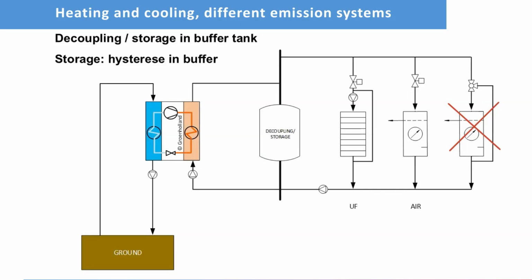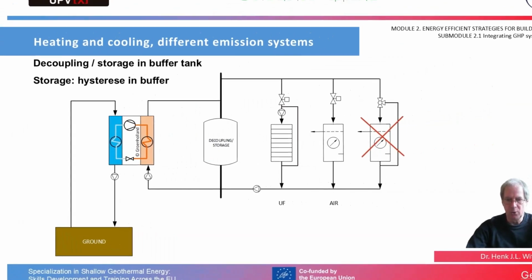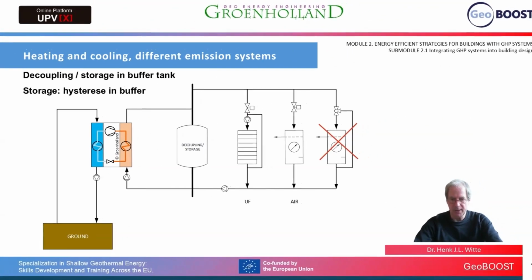On the far right, we can see an air handling unit with a bypass valve, a 3-port valve, where the capacity on the fan coil unit is controlled by bypassing part of the flow and mixing that into the return to the storage tank. In this case, we'll get a small temperature difference on the building loop, which is not recommended.